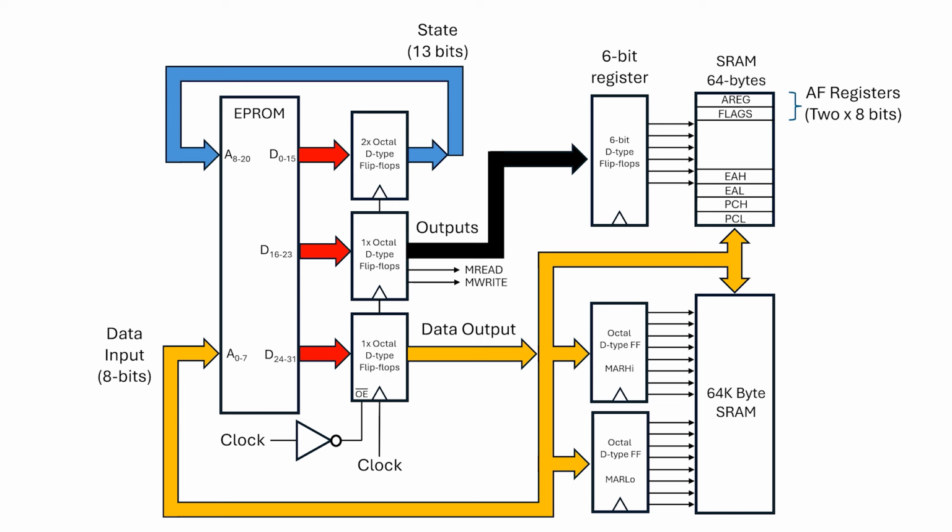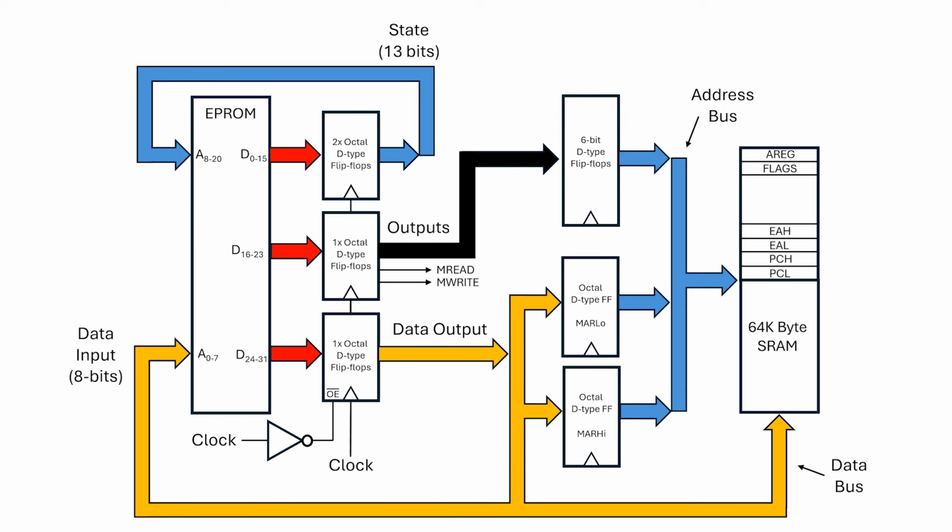I tend to call the top memory the notepad, although technically, the top memory and the bottom memory together are required for Turing completeness. But it turns out that the finite state machine never needs to access both memories at the same time, and we certainly can't read them at the same time because they're both connected to the same data bus. I can actually combine these two memories into a single static RAM device.